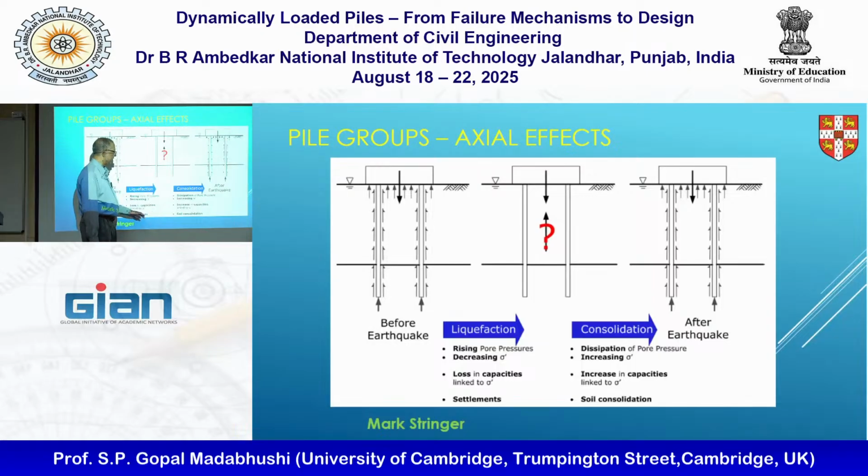After the earthquake is finished and the soil consolidates, we more or less recover what we had here, right? So pre-earthquake and post-earthquake, you will regain some level of pile cap bearing capacity. You got the shaft friction back. You got the end bearing back. Earlier I forgot to mention you also will have some level of cap bearing, which in most designs, normally the designer will ignore the pile cap capacity and they'll say that is conservative.